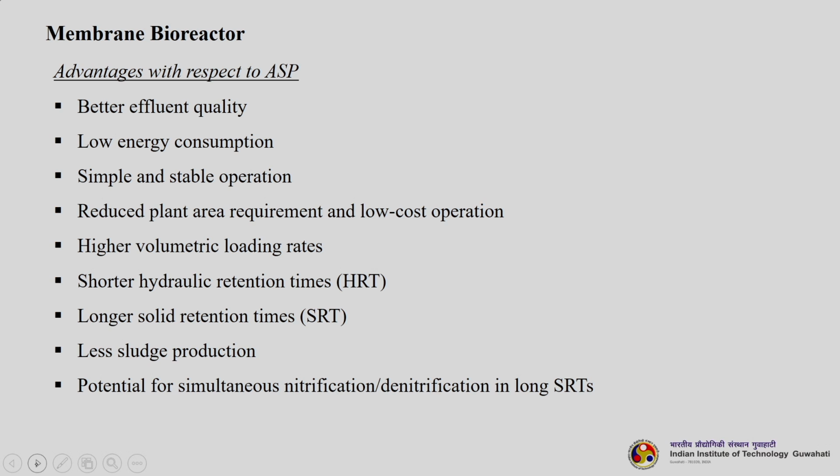Of course, there is a reduced operational cost, higher volumetric loading rates, and the best two things are a shorter hydraulic retention time, HRT is very small, and a longer solid retention time, SRT is very high. This is what we actually need in biological systems. There is less sludge production than in the activated sludge process, and potential for simultaneous nitrification denitrification in case of long SRTs. However, it has some disadvantages. The most important disadvantage is membrane fouling.